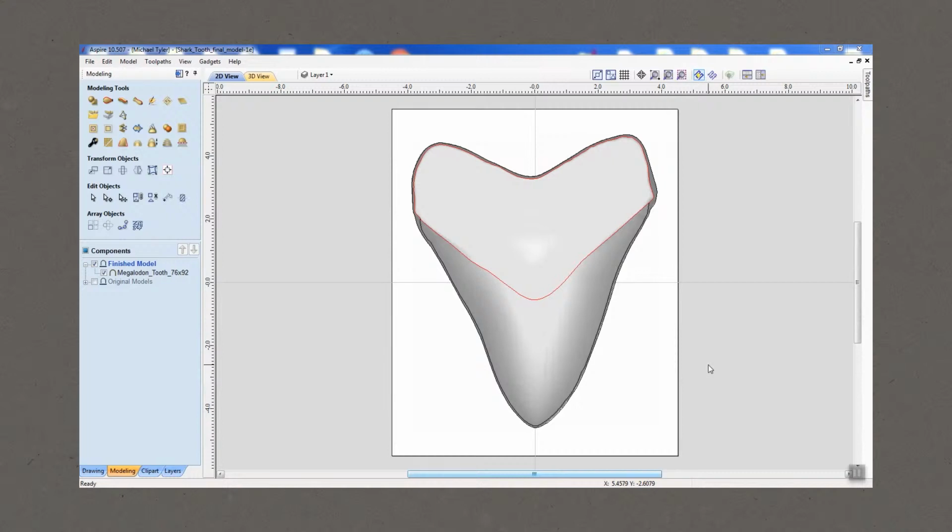We're going to carve this out of 3/4 inch thick material, and the model itself is 3/4 of an inch. So it's going to carve all the way through around the perimeter of this model. So in order to have that held in, assuming we don't have a vacuum table, which I do not have, we're going to need some tabs to hold that piece in.